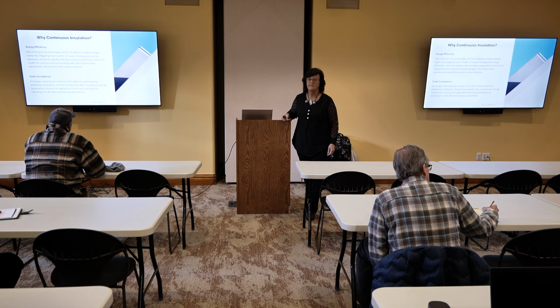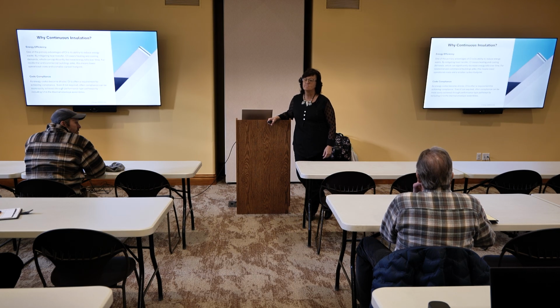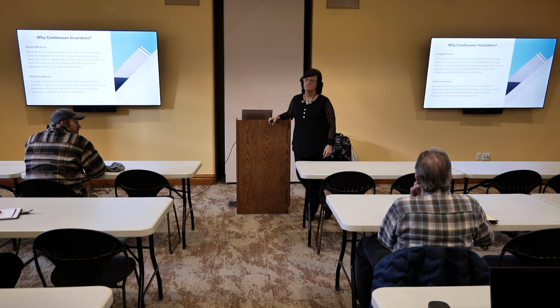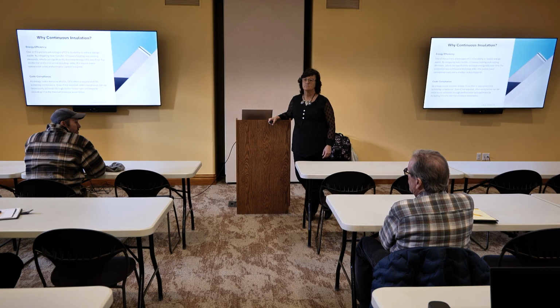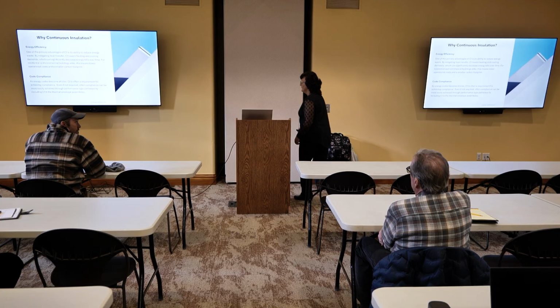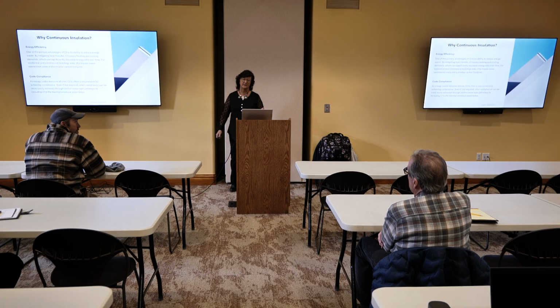It seems like with the code updates, at least in our climate, it's really pushing spray foam insulation in the cavity, R30, versus continuous, because the continuous has to go up to 7.5, or really for ZIP panel it'd be 9. So it is getting harder to do. Yeah, especially for commercial. For residential, what are your options?